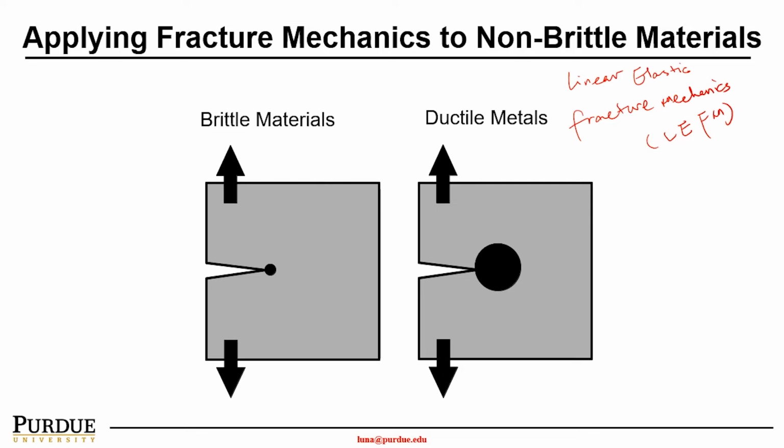As shown here, in a brittle material, because you have a lower K_IC, the fracture toughness, the critical energy release rate is low, so the tip can quickly grow new surface area. In a ductile material, because your K_IC is high, you have a higher G critical, or G_IC.